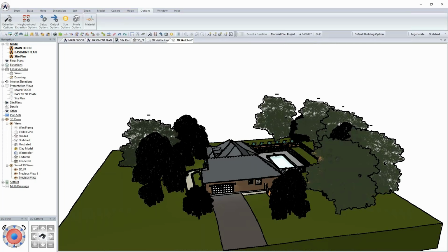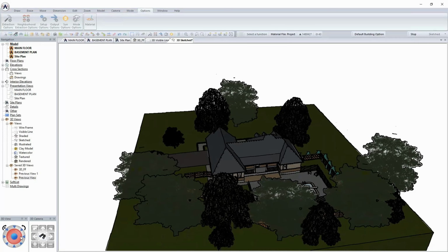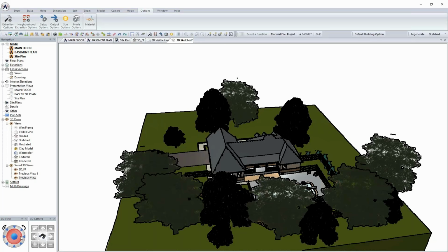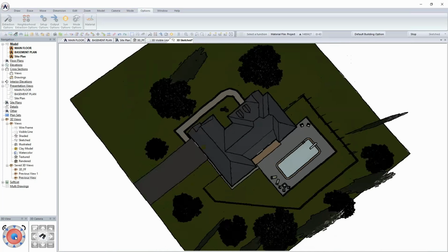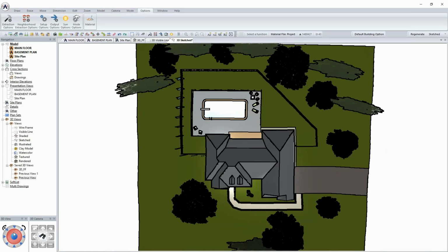The key is, you'll notice, in order for me to change the incline, I actually moved my cursor from here down to the front view of how you would think of this. Because again, remember, the red circle on the 3D viewer treats the current view as that front view. So if I click over here, it's going to rotate me by 90 degrees and adjust that incline. Lastly, the blue circle is always kind of a top-down view. Okay, so that's what it's doing there.